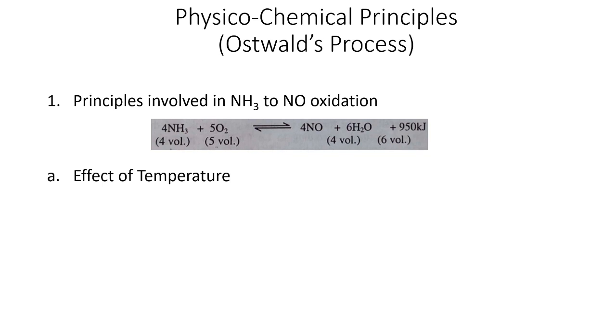And the second problem is decomposition of NO2. The NO2 which is formed can be decomposed. That is another problem if you increase the temperature. So at higher temperature, not only does ammonia get oxidized to N2, but decomposition of NO2 is also a big problem. So you cannot increase the temperature. Experimentally it is found that 750 degrees Celsius is the optimum temperature, and the efficiency of the